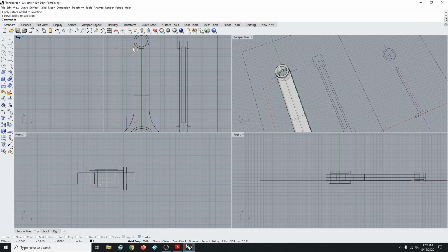So we want to make an object, or a tool really, that is what we're doing. We're using these red lines to make a shape that we can take a difference with later. So we collect all those guys and then go Edit, Join, and then escape. Click it again to make sure that everything you need is there.